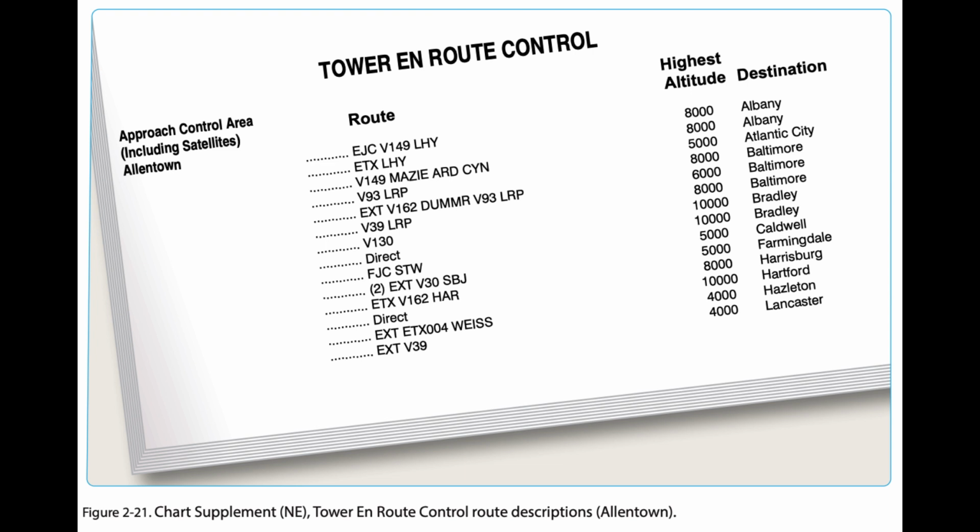When a navaid or intersection identifier appears with no airway immediately preceding or following the identifier, the routing is understood to be direct to or from that point unless otherwise cleared by ATC. Routes beginning and ending with an airway indicate that the airway essentially overflies the airport or radar vectors are issued. Figure 2.21. Where more than one route is listed to the same destination, ensure that the correct route for the type of aircraft classification has been filed.